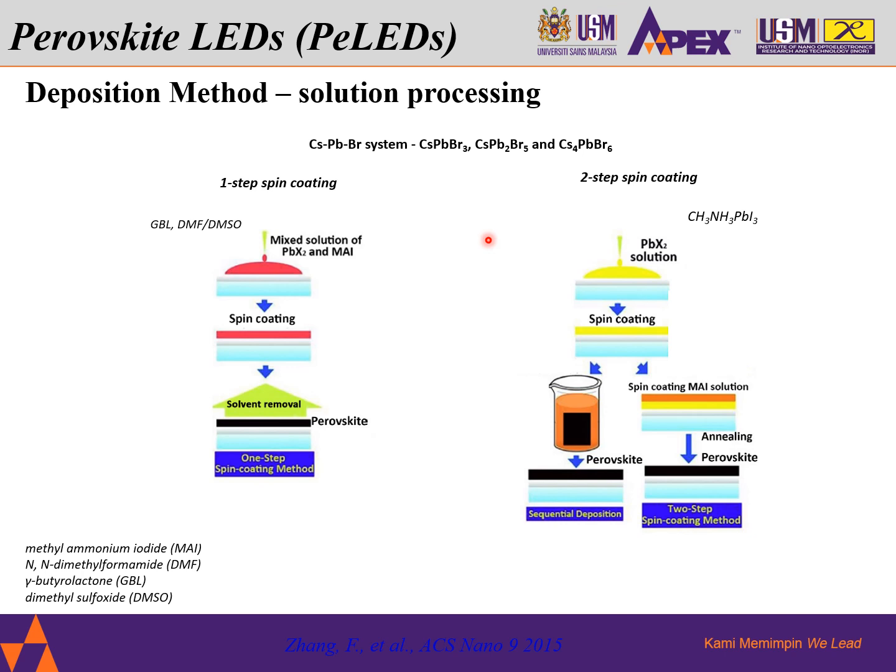Here, solution processing is most used in the synthesis of perovskite-like compounds in the CsPbBr system, which is CsPbBr3, CsPb2Br5, and Cs4PbBr6. Solution processing methods have the advantage of being fast and easy to process. Moreover, of course, they are low cost and compatible with roll-to-roll device production.